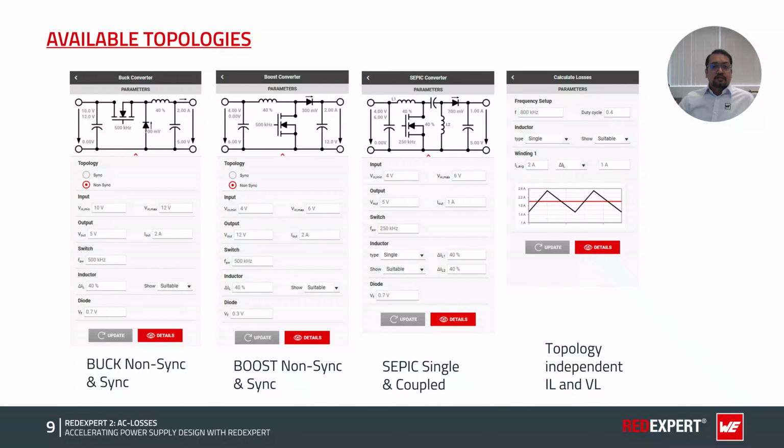REDEXPERT supports a wide range of converter topologies, not just the common ones. It supports buck and boost in both synchronous and non-synchronous mode, SEPIC for both single and coupled inductor variants, and a topology-independent mode where you input the inductor current and the voltage directly. This last option is specifically powerful for engineers who are working with custom topologies that don't fit into the standard converter topologies.